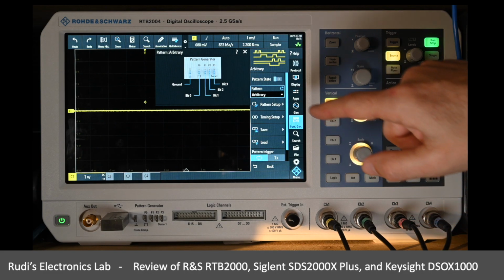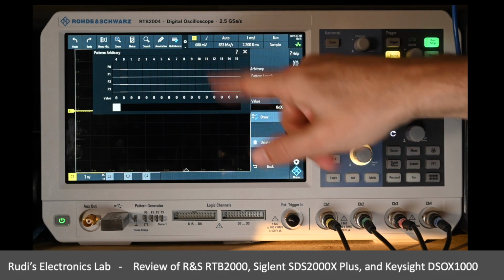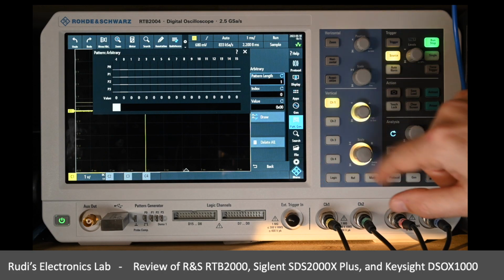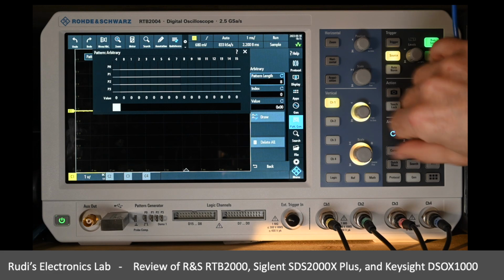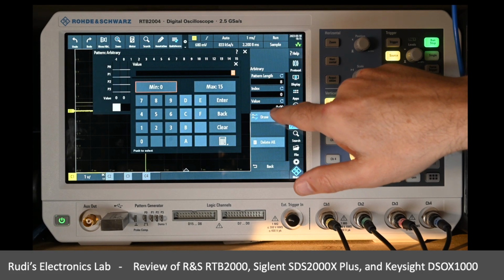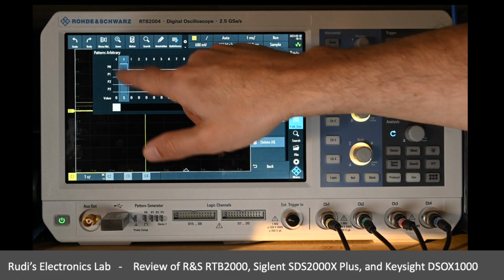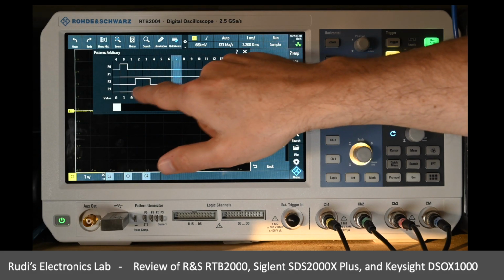So let's first take a quick look at how we can do it ourselves. You go to the pattern setup and it's rather simple. You get to see the 4 output lines. The total pattern length actually can be up to 2048 values here. I'm just going to put 8 values now, and you can create values by entering them here via a screen. But perhaps the easier way to do it is to use the draw function and to just draw those areas where you would like a 1.